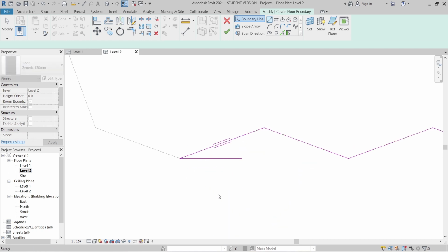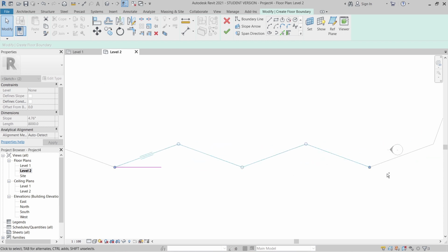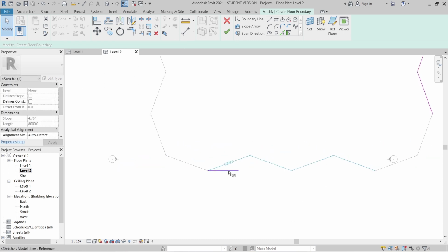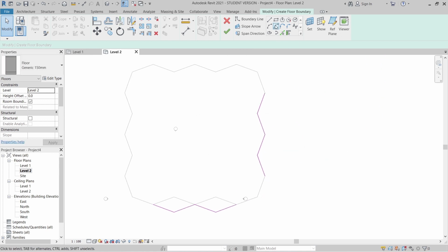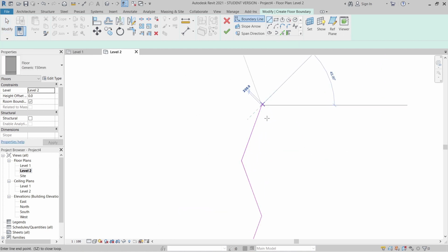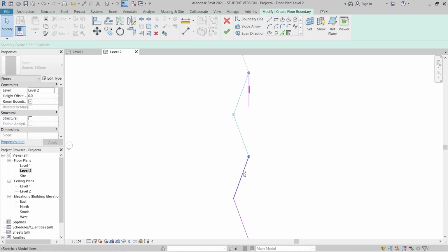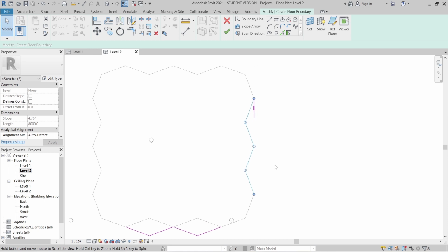The reason I draw that is because we need to mirror here. When I draw it out, you will see that for mirror, as you can see, and then I'm going to delete. Make sure you hold the Control key, just reminding you, for multiple selection. And here again, select our fourth point here and mirror again, or you can go to your toolbar there. Here is our mirror and here is our draw mirror. Got pencil here.